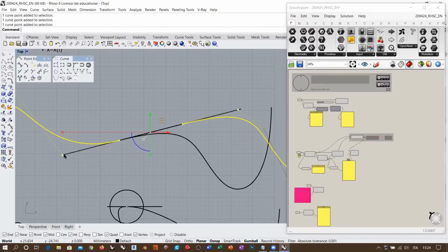Now, if I consider this sequence of 4 control points, what I would do if this was one single command execution, by aligning 4 control points, I am defining this tangent here for this final segment, and then I'm starting on the same tangent, defining the same tangent, but on exit, right? What happens in between?